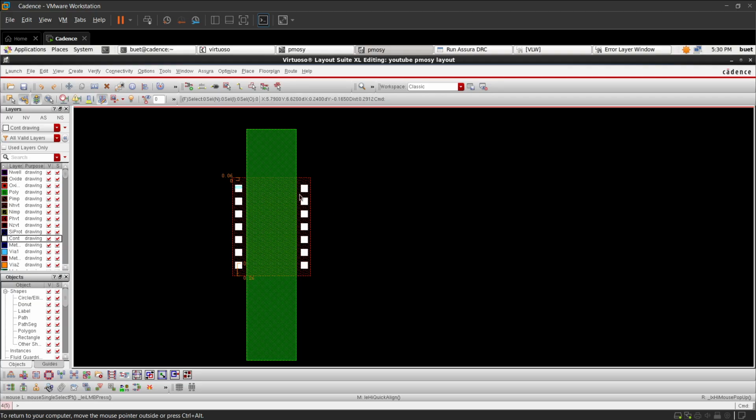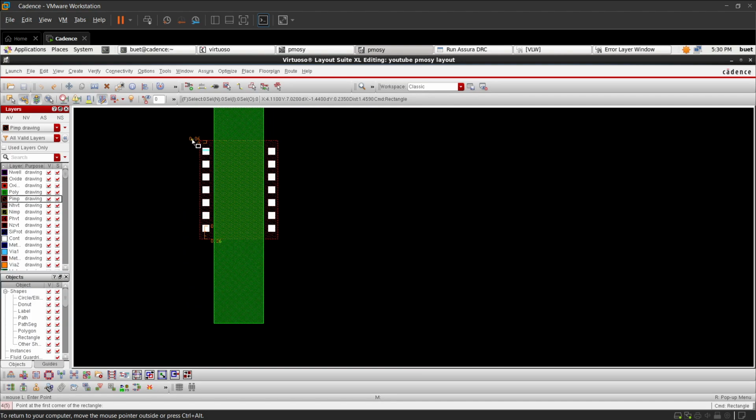So this is all about how to place the contacts on our layer. Next, save. Next thing, we are supposed to cover this whole thing with our P implant, because we have been doing our PMOS design. The PMOS is going to reside in the N-well. Next, we are supposed to do the N-well formation also, but right now we're looking into P implant. So go over here, select the P implant, press R, and just draw it.